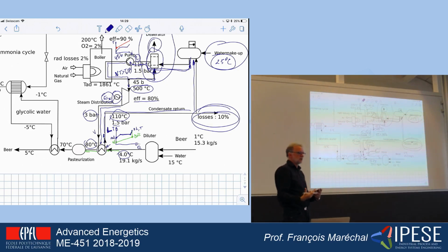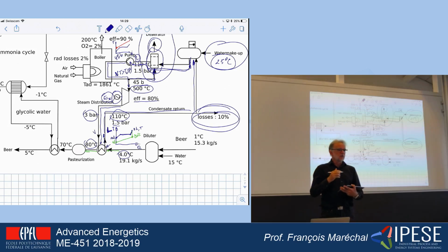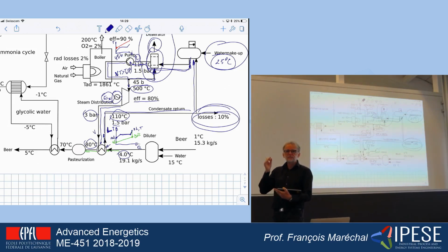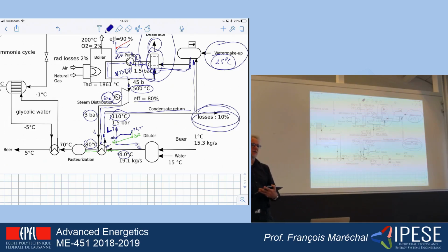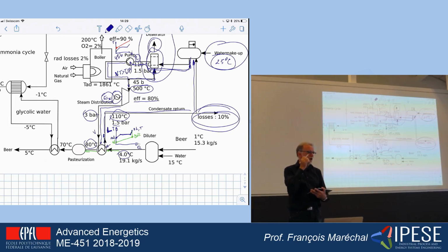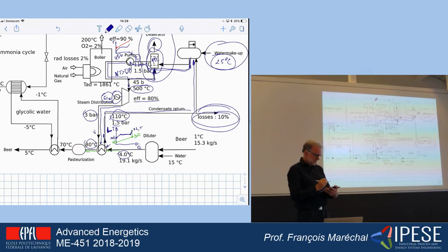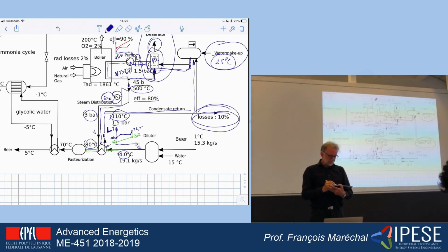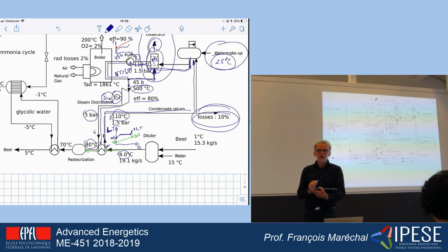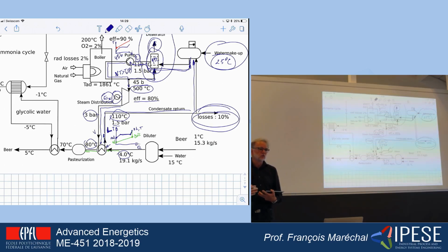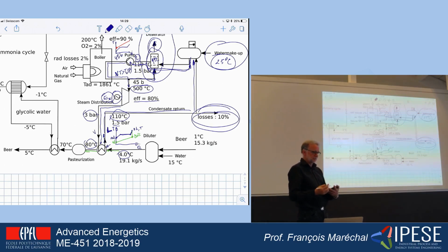That's what we name the deaeration. It means that we are sure that if we boil the water, there will be no other form of gas in the liquid. So everything that is lighter than the water will go into the gas, right? And so we stop here. Typically, there is a set point when the pressure is 1 bar or even a little bit higher, and the gases will leave the system here. Okay, and this is the reason why we have to do this deaeration.